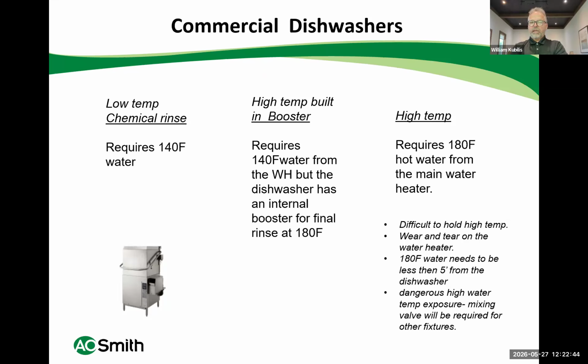Now, I tend to discourage this. The reason is that it can be difficult to hold 180-degree water out of a water heater, as somebody could have been filling a sink or using some other high demand, and the water temperature has dropped a little bit. Then there's wear and tear on the water heater. The more you increase the temperature of the water, the more corrosive it gets to be.